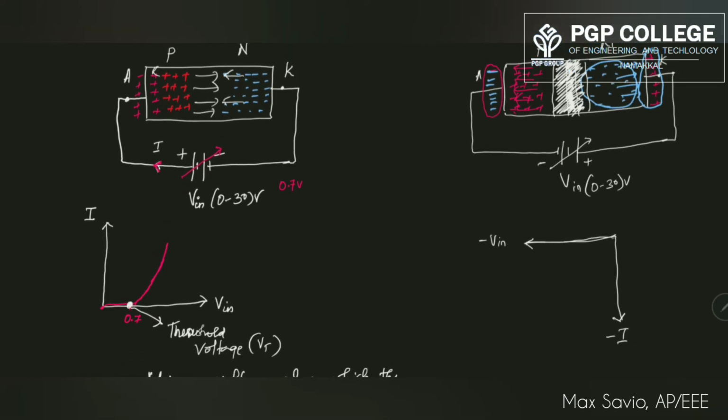From the point of 0, as the voltage increases, there will be a very, very small value of current, until at some point the voltage is negatively increased to a very great value, and immediately the breakdown occurs and the current starts to fall, increasing on the negative side to a higher value while keeping the voltage constant. This point is now called the breakdown voltage. It usually happens in the reverse bias.